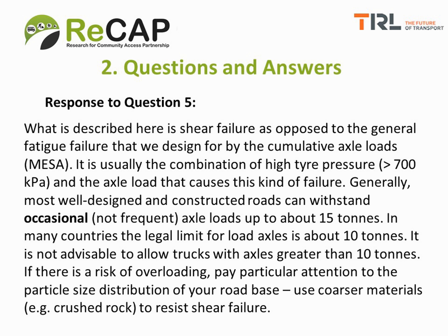The sheer difficulty of negotiating around rural roads often stops operators from using them with large vehicles and very heavy loads. But of course, there will always be cases, as the questionnaire says, where heavier loads are used. And as I say, if you think that's going to happen more often than normal, you would have to use better materials and effectively design the materials for essentially the higher traffic levels. I don't think there's any way around that.